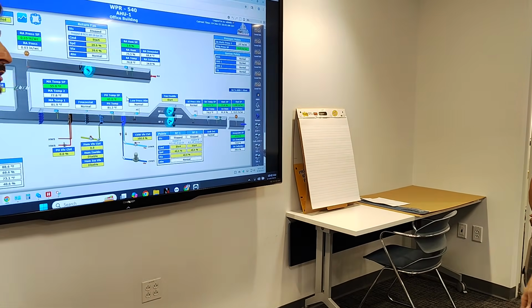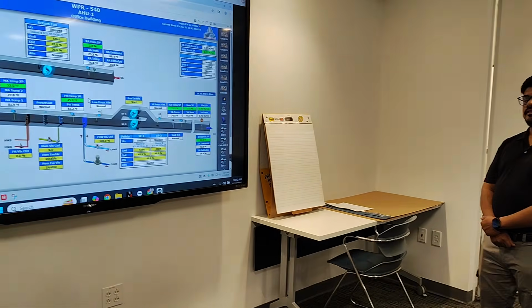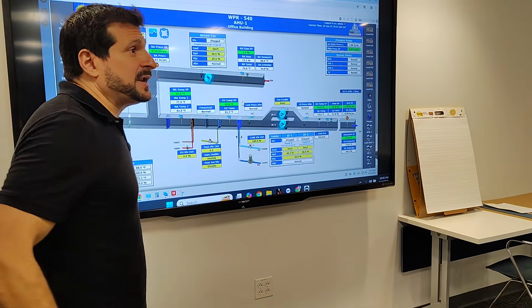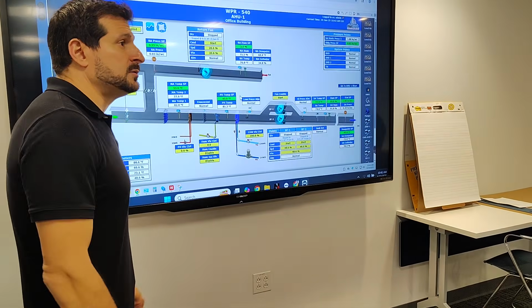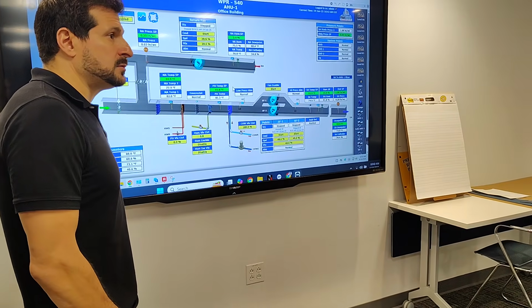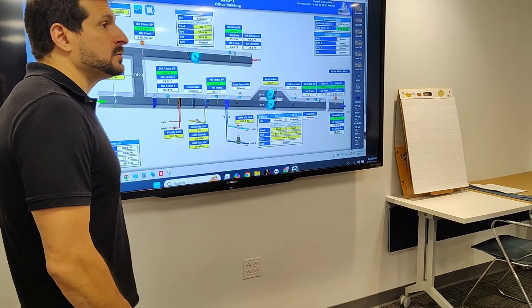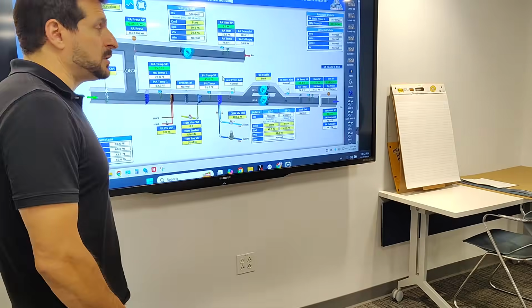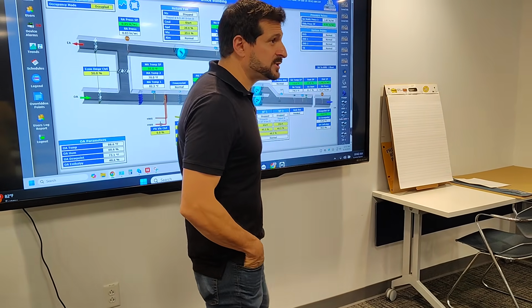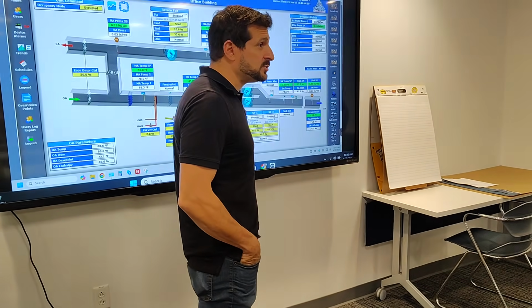No. So when they say it's 79 degrees upstairs, what are we going to do? When they say it's 79 degrees, you have to go upstairs and figure out how to get your chilled water to be colder. Okay, we'll do that. But let's say we get the second unit on, and now it's 65 degrees up there. We're going to need to make adjustments. And all you're going to be able to do is adjust this temperature here, this static pressure set point here, and see what the unit does.